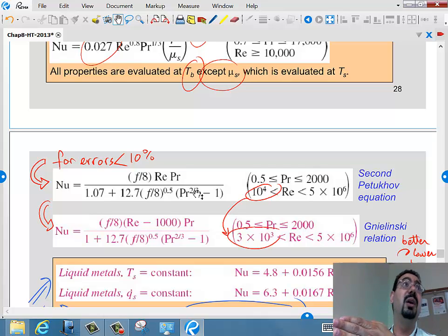So in the exam, if I tell you the Reynolds number and you pick a correlation that's around that, or it's valid for that range, you are free. You are set. You don't have to worry. But if the Reynolds number was 5 times 10 to the power 3, 5,000, and you end up using this, and you ignore the fact that, well, this one is actually more appropriate for that range, then you lose points over it.